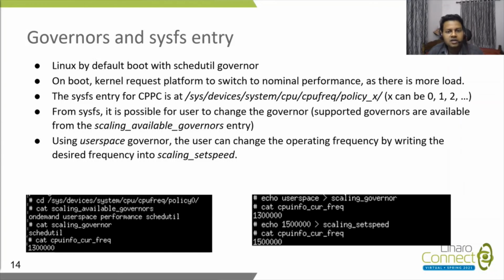So the schedutil governor will request nominal performance, and once boot completes, the CPU load will be less, and the schedutil governor will request the platform to switch the CPU to lowest nonlinear performance. So that's about the schedutil governor.